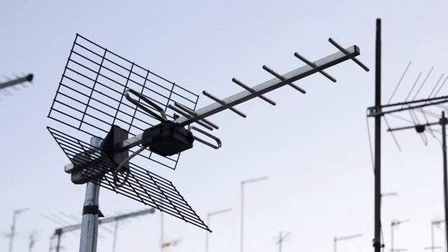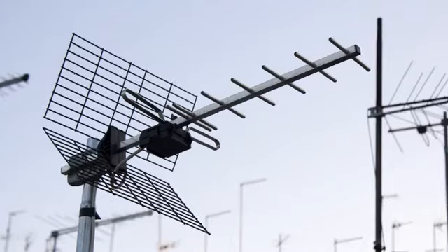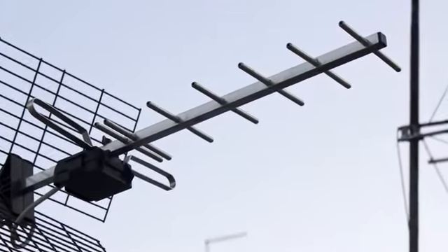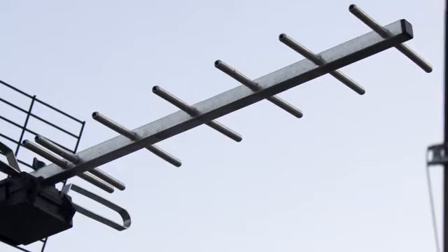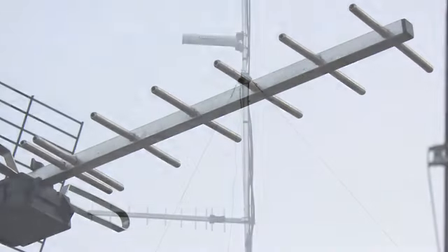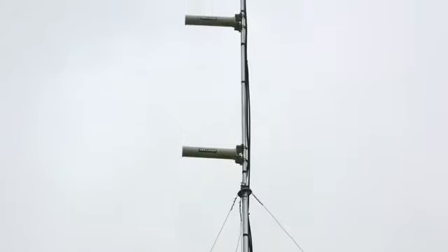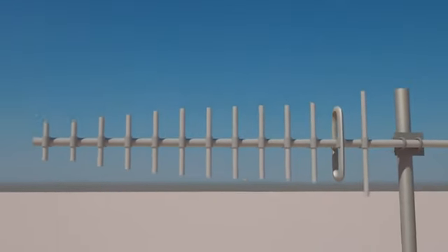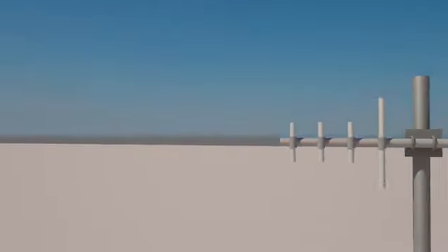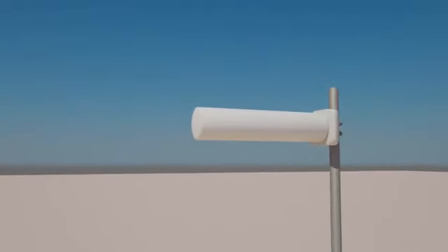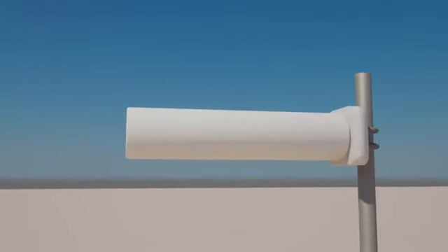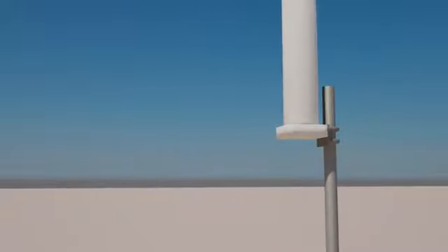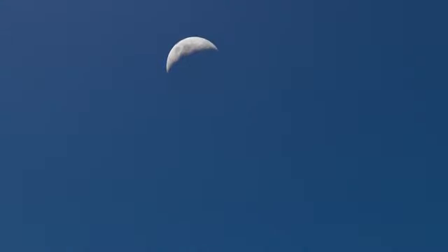A Yagi antenna is composed of an array of linear elements parallel to one another and attached perpendicular to and along the length of a metal boom. This causes the antenna to radiate energy in a beam out the end of the boom. The actual pattern depends on the overall geometry, including the number of elements, element spacing, element length, and so on, but generally is proportional to the length. So although it may look like an omni antenna, it does not function like one.